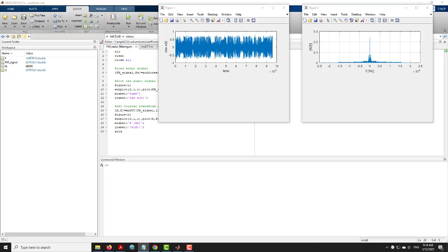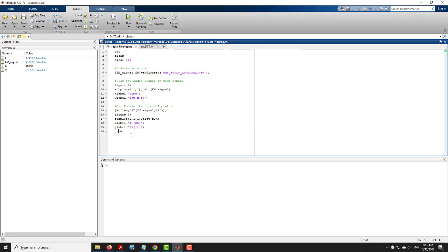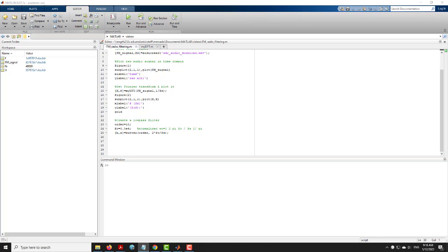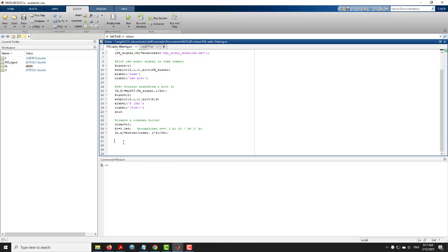Now we can start playing. I'll let MATLAB design a digital low-pass filter with a cutoff frequency of 5 kHz. This time I'll select a Butterworth filter since it's maximally flat in the passband. The order of the filter is 15, so MATLAB returns the transfer function coefficients of the order 15 low-pass digital Butterworth filter. The A vector has the coefficients of the transfer function's denominator, and the B vector has them for the numerator.